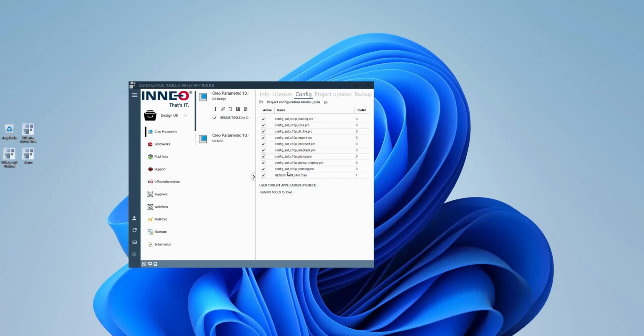And then the next one, the one that's got the underscore dir underscore file in it, will be an example where people could have different file path locations. So like I said, maybe one is on the C drive, maybe one's on the D drive or a mapped drive, and you can then have all these different files for the different startup commands or different areas or divisions in your business. And when the user starts up that configuration, what the starter tool will do is go and take all those different configuration files that you've specified for that unit, combine it into a single file, copy that into your text file as your config.pro and then start up that configuration.